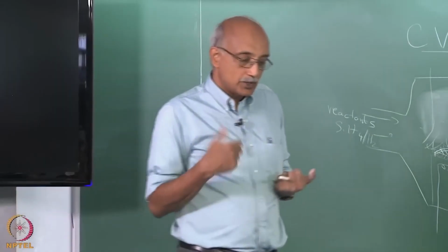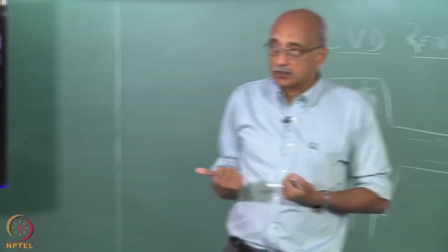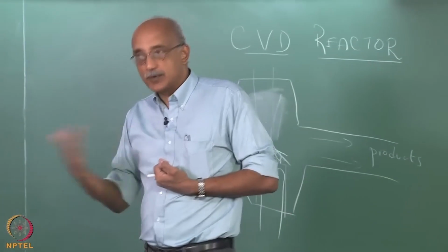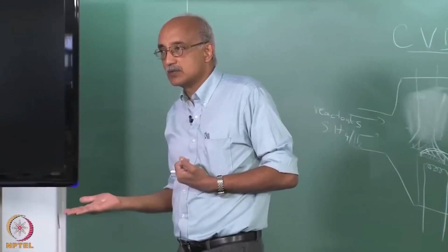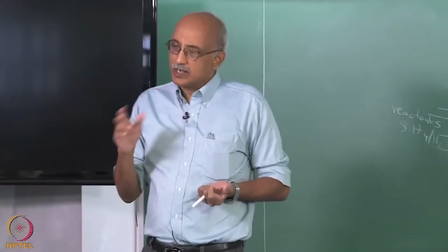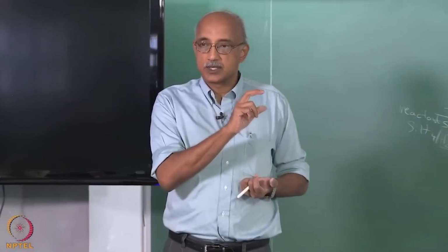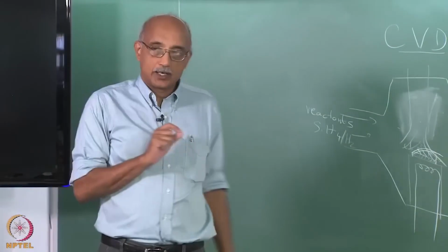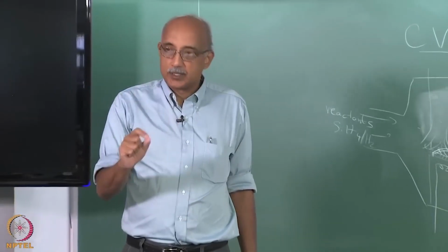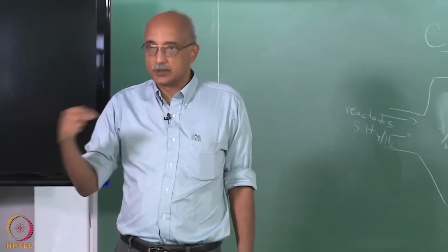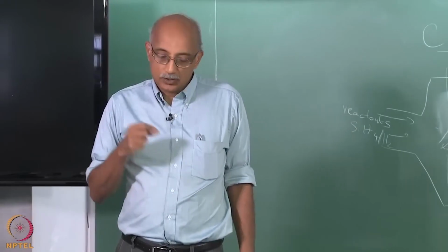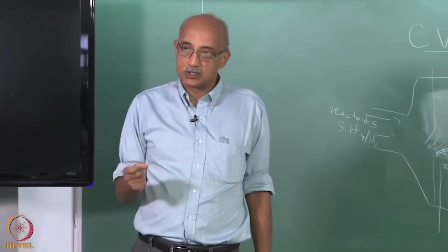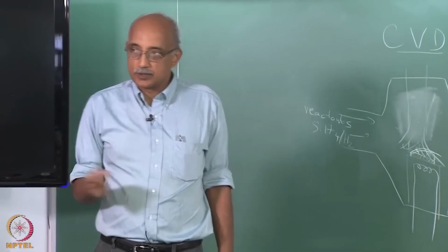And so, whether you are trying to do modeling of a CVD reactor or the actual operation, control and optimization of a CVD reactor, you not only have to pay attention to the individual steps that are involved in the formation of the film, but you also have to take a close look at how each step in your mechanism is coupled to the next step and try to obtain a system wide solution that works for you.